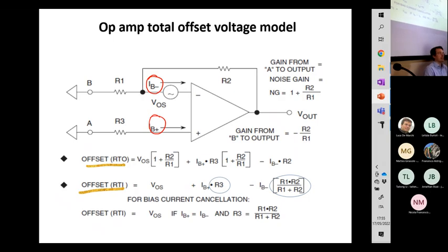This biasing current also means that the input impedance of this device is not infinite, and can be combined with the offset effect to determine the global output response, which is far from zero despite having null inputs.